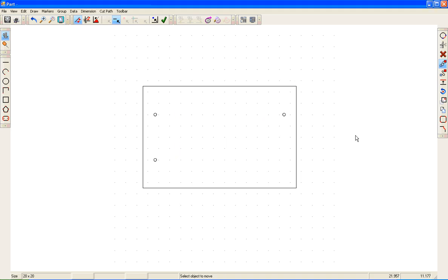Okay? So that is the Set Reference Point. It will allow you to place an object from a grid point, from the end of an object, from a marker, from an intersection, or just any point out there. It uses all three input methods, but it'd probably be easiest to use relative.